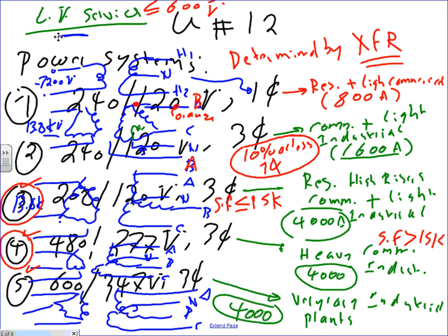For example, I always use a pump house, a water pump house full of 240 volt, 3-phase pumps pumping the water to the city. But inside is just a house full of pumps, pumping from the wells and pumping it all the way to the cities, right? Now you need to power them with 3-phase 240, but inside the house you need a couple of convenient 120 receptacles on the walls and a couple of lights that you're burning at 120.